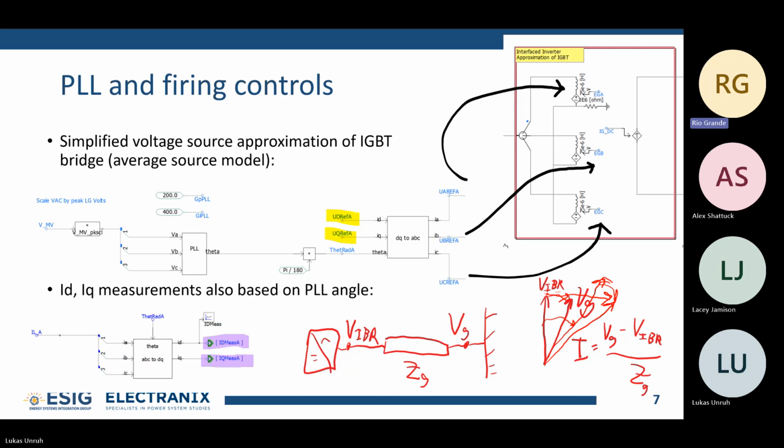As you can imagine, there are a few critical parts of the controller that play into how this voltage phasor moves. That's the phase lock loop and the inner current control loops, both of which you can't really represent properly in the phasor domain.